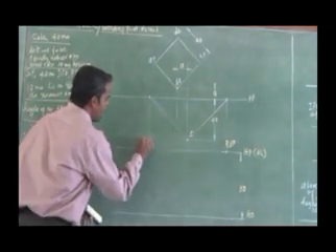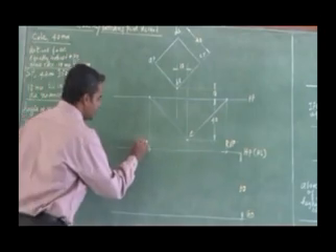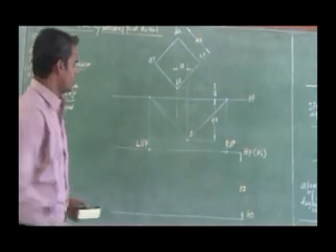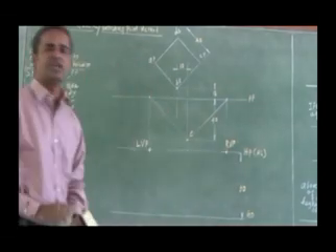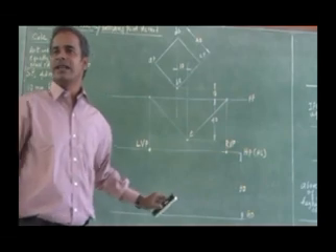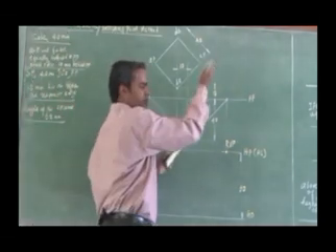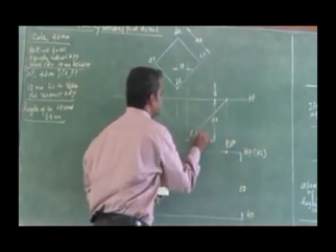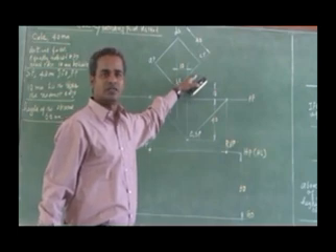So this is going to be another vanishing point. What is this vanishing point? It is on the left side, so the left vanishing point. So I have got two vanishing point locations, the right side and the left side vanishing point. Is it clear? To obtain a vanishing point, draw parallel lines from the station point, one to the parallel face and one to the inclined face.